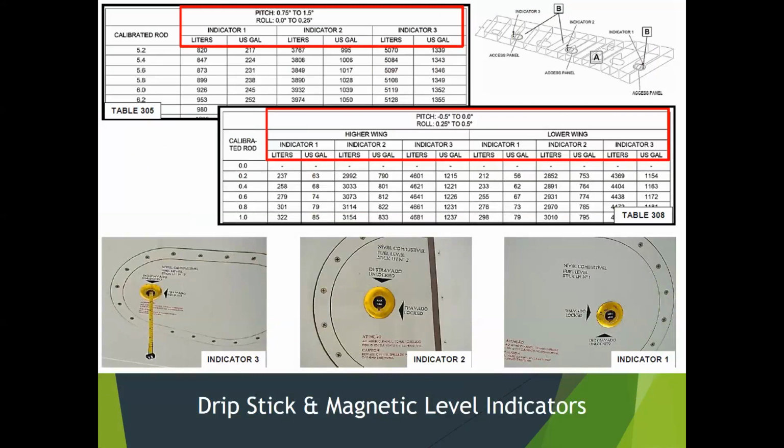Temperature. It can't just be temperature because it could depend on if you have Jet A1, if Prist was added or not. Density. You need to know the actual density of fuel. All those things, temperature, but also does it have Prist mixed in it or not? Prist is for winter operations. It's an anti-icing agent. Is it Jet A? Is it Jet A1? Is it some other fuel? There are different additives added to jet fuel by different refineries that can slightly change the density. So since we can't know the density just by knowing what kind of fuel is in there, we have to measure it.